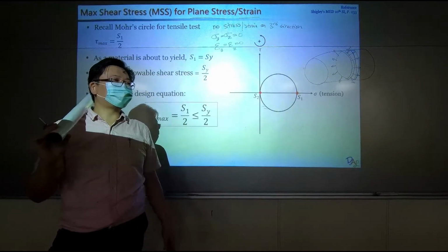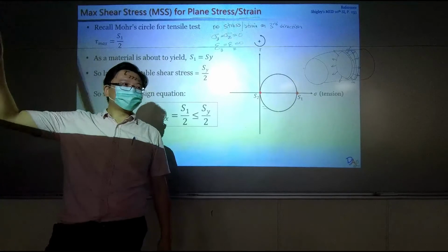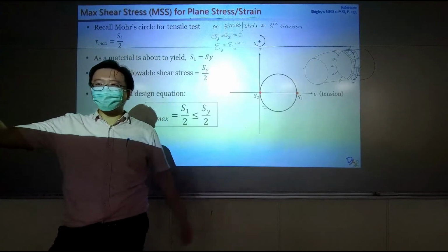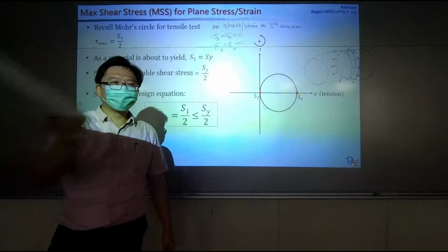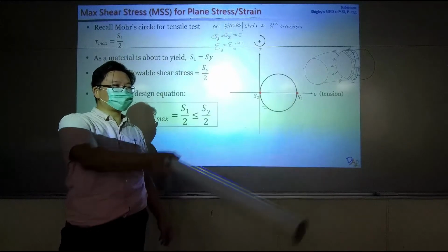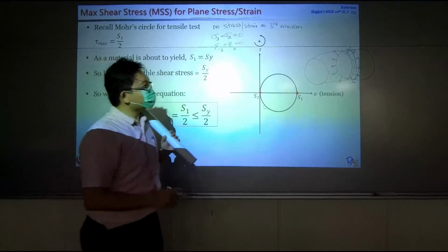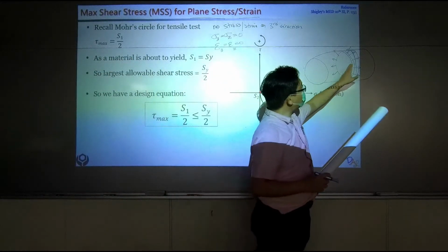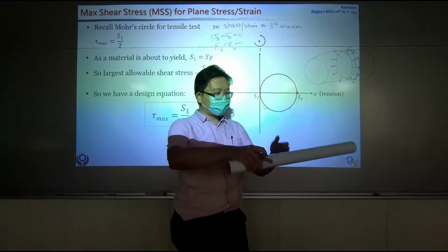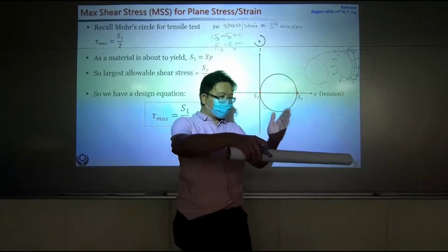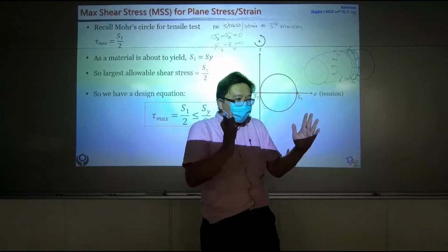It's a 50-50 guess, right? Who thinks it's a plane stress problem? Just no punishment, just a random guess. Plane stress? Okay, one. How about who thinks it's a plane strain problem? Okay. More votes. Good. It's the plane strain problem. So how do I memorize this? The reason why these two are exactly the same is because those cuts are stacked inside a huge material. They are being squeezed within this huge material.